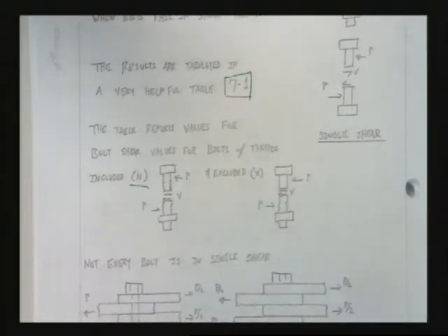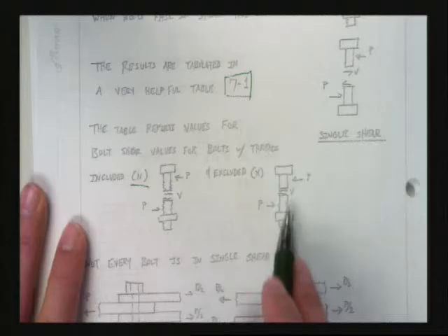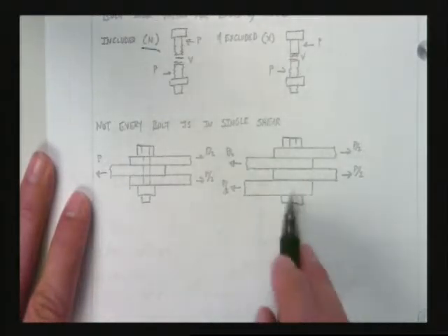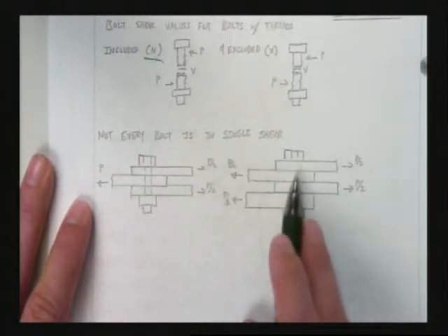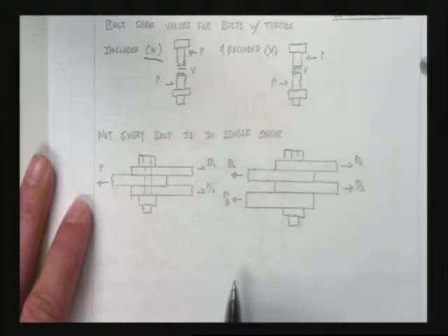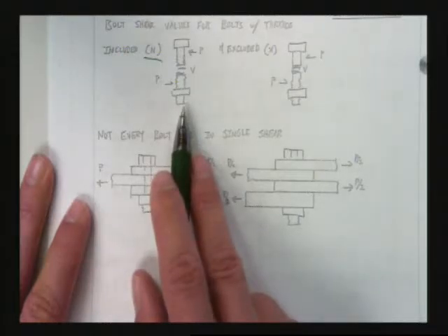Because we don't have to do any geometry calculations to see, for that size bolt, what is the shank length? And then what is the geometry of my actual connection? How far do these plates actually come down? And where do they bear? Also, guess what? I'll have parts that may have threads included, and then I may have parts of my connection that'll have threads excluded. Guess what? Make the easy assumption. Assume they're all included. You with me?